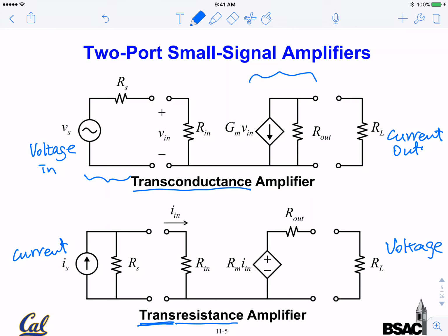The reason we have all 4 of these is that we have a need for all 4 of these. Sometimes we want to convert a signal which is primarily current in nature, such as in your lab 3, I think, where you are flashing LEDs, you pick up your signal, which is photocurrent, and you want to convert that to voltage.